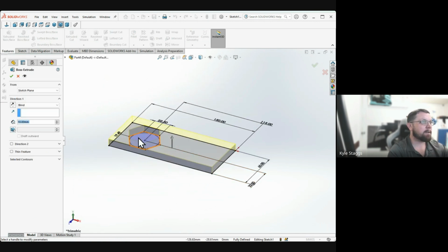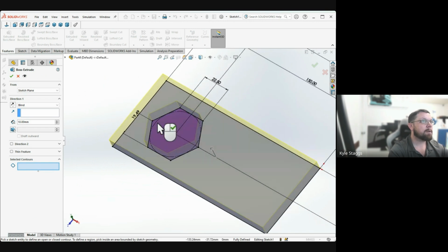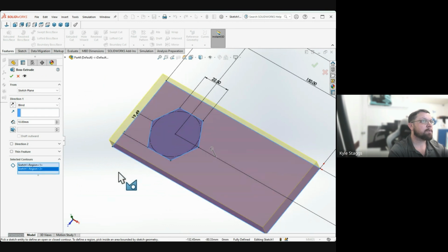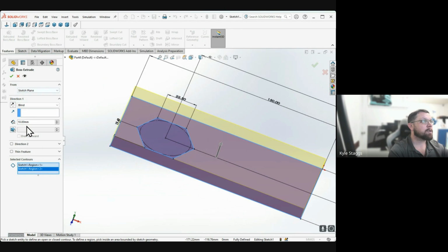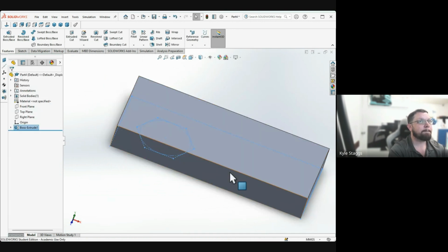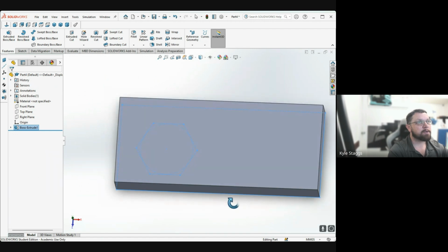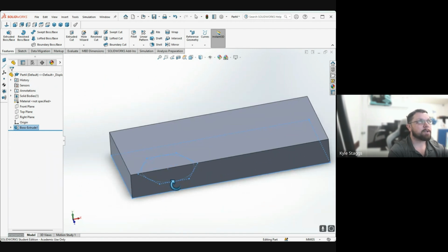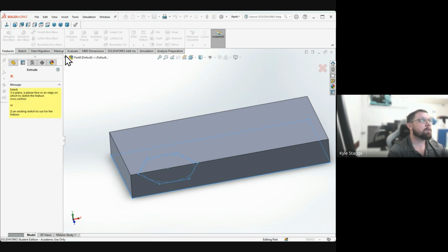And let's say you extruded both regions. So this region and this region. And we extruded that by, let's say, 20 millimeters. Okay. But the object you were supposed to draw has a hole where that feature is. You can do the reverse by hitting an extrude cut.